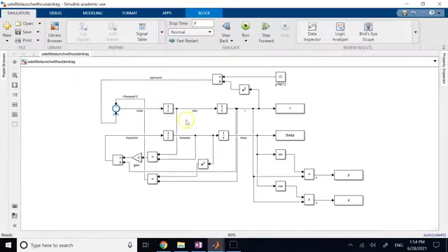and this is exactly what you can see here in Simulink. This is R dot at time 0, which is 0. Remember, I said no radial velocity at launch time. This is R of 0, which is R naught. This is theta of 0, which we consider 0, and this is theta dot at 0, which is equal to V naught over R naught.